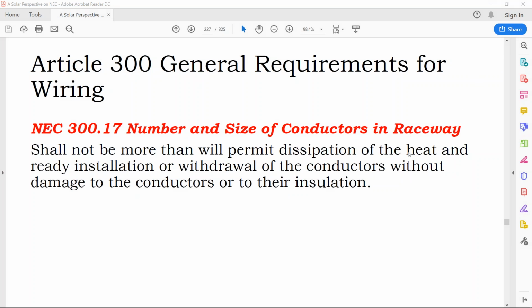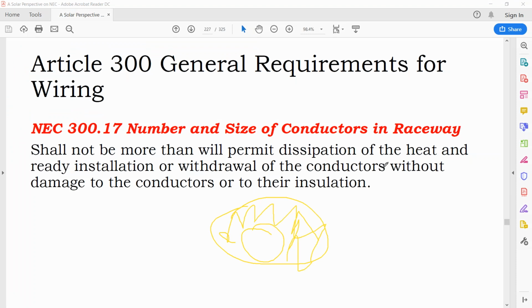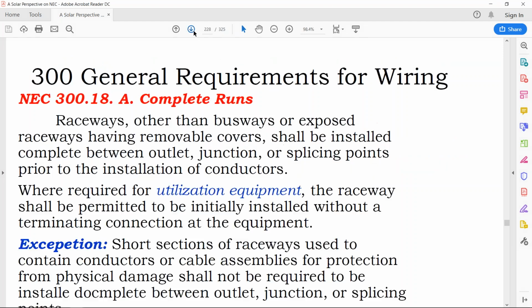But the point is, you need enough empty space in your conduit for your conductor to be able to pull through and also dissipate heat. And so typically your conductor fill is like 30% to 40%, depending on how many conductors you have inside your raceway. So as an engineer, if I'm thinking, oh, the conduit is 60% empty, that's a lot of empty space, you could squeeze another cable in there. But you actually need that empty space in order to pull the cable through the conduit and fitting without scraping up the cable jackets.